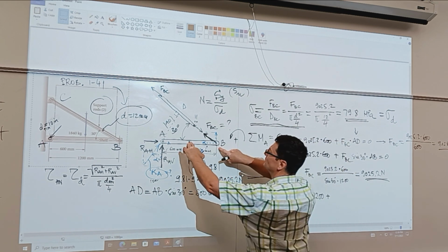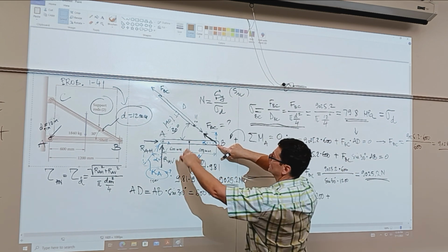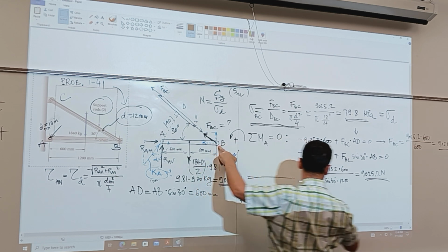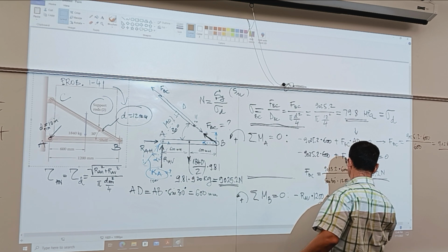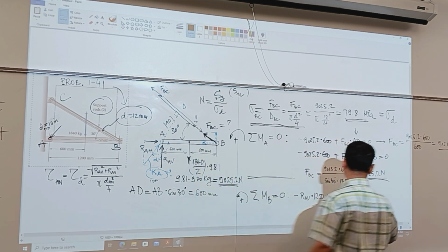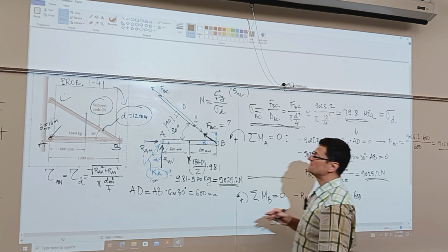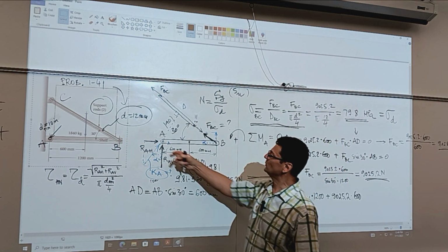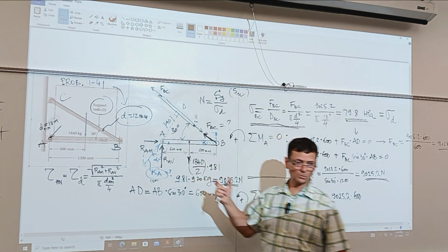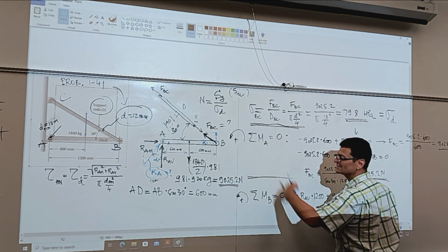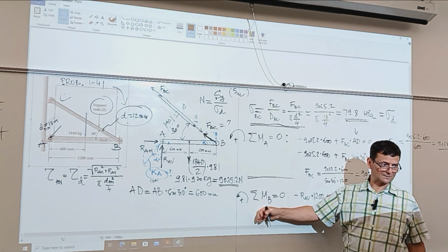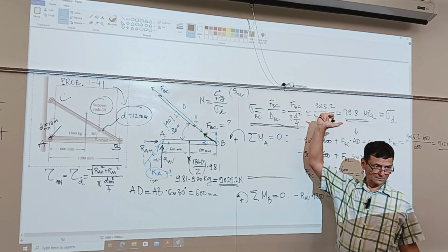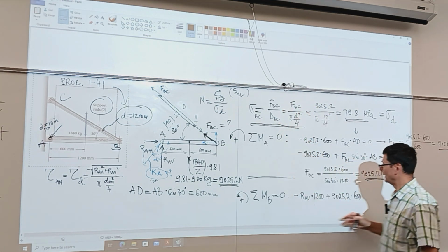And then I have the positive moment, the counterclockwise direction, of this force, 9025.2, times its arm, 600 millimeters. By the way, here, nothing to do with millimeters and megapascals. You can use meters, not to carry zeros with you, because it's different business here. We do statics. When we calculate stresses, like I said, millimeters, megapascals, newtons, the equations are balanced.